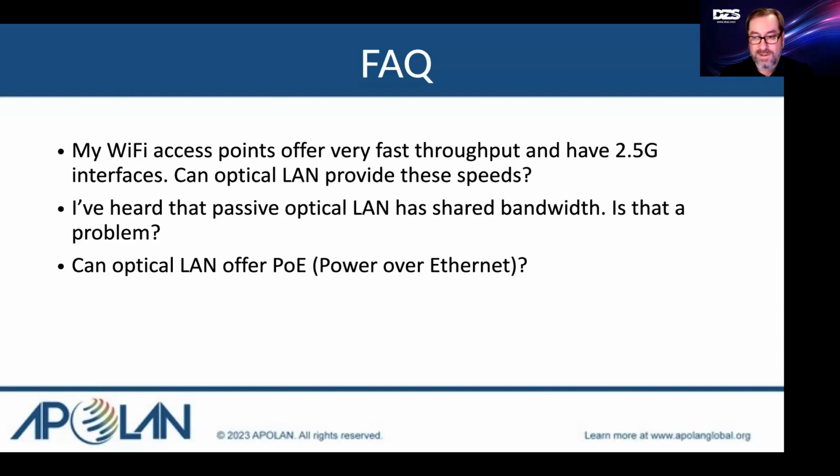Absolutely. You've already covered that the ONTs can provide PoE to the endpoints, and most of the requirements for PoE range from Wi-Fi access points to security cameras to door locks. There are many applications where you would require PoE, and there are also many levels of PoE, which all vendors try to adhere to. The latest being PoE++, which is 60-watt PoE, available on almost all ONTs that offer PoE these days. And it'll supply that 48 volt, just like a PoE closet switch would.